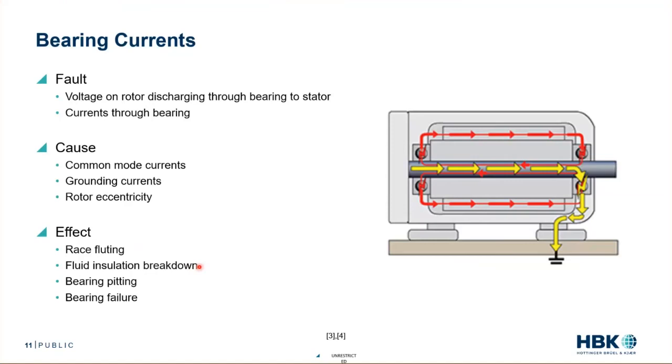If the bearing has fluid in it, you could effectively cook the fluid, and now you're no longer getting the really good protection that you were looking for. If it's ball bearings, the bearings themselves can become flat on edges. And again, it's no longer operating as well as it can, and this is going to create heating. This is going to create more faults or more short circuits, and it's going to be an increasing failure until you have a catastrophic failure. Ultimately, again, resulting in bearing failure. And again, this is voltage building up on the rotor, discharging through the bearings to the stator. That's bearing currents.